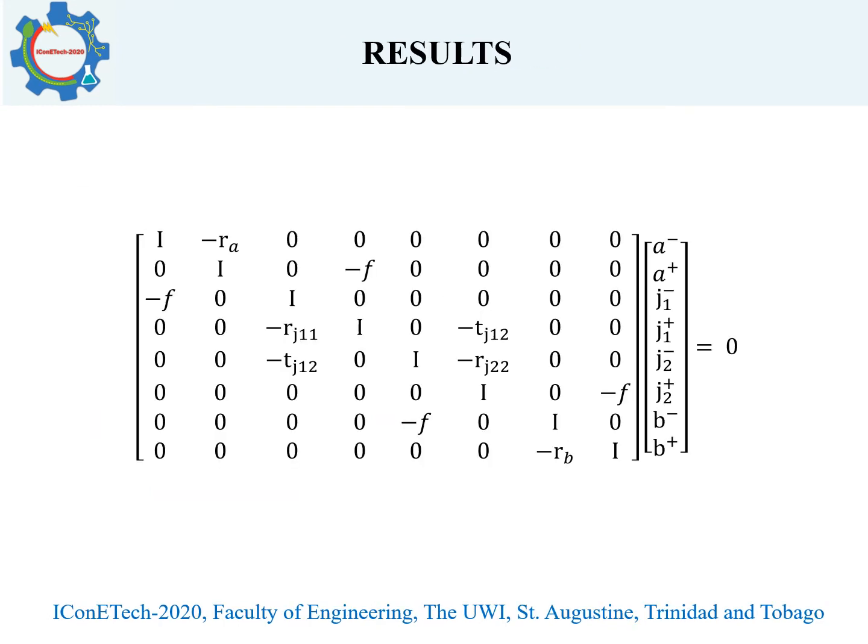The wave relations on the previous slide can then be combined to form a wave coefficient matrix, A, and a wave component matrix, C. It is important to note that what is shown here is a simplified representation of the true global matrix. When in actuality, each element in this 8x8 matrix here is actually a 3x3 matrix, so the overall global matrix would be a 24x24.